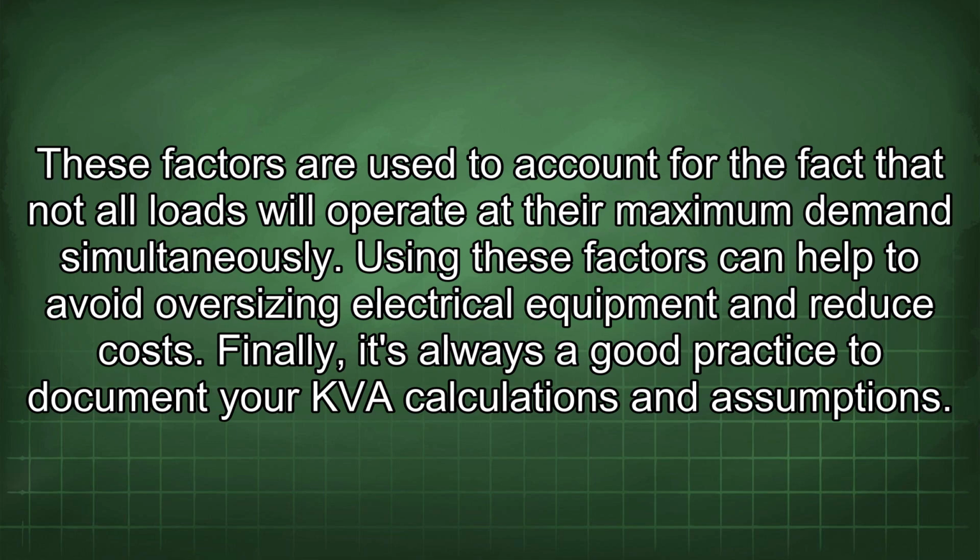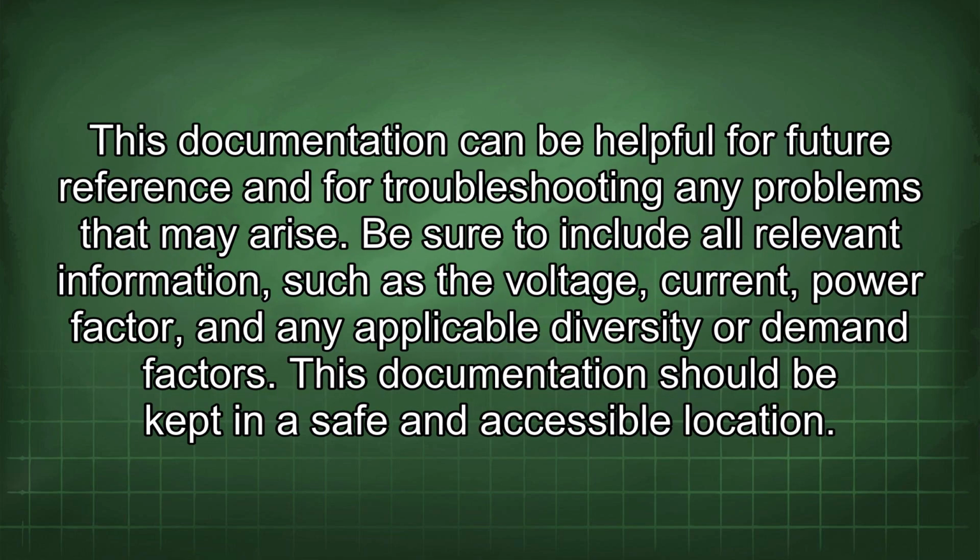Finally, it's always a good practice to document your KVA calculations and assumptions. This documentation can be helpful for future reference and for troubleshooting any problems that may arise. Be sure to include all relevant information, such as the voltage, current, power factor, and any applicable diversity or demand factors. This documentation should be kept in a safe and accessible location.